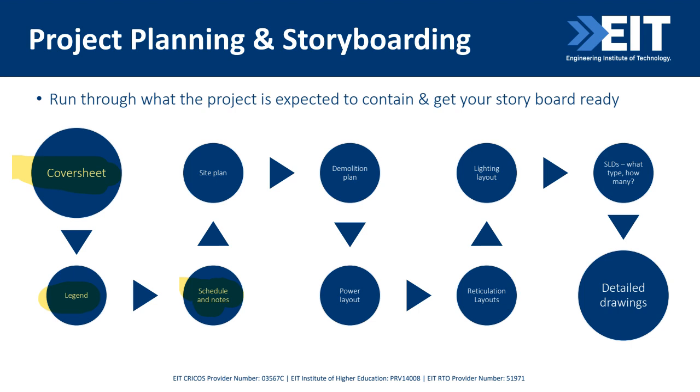One of the key items is a site plan. So this gives you context of what you're doing in relation to the larger area. So it's very zoomed out, you could say, and it gives positions and maybe external information like pits and conduits and street lights. If you're demolishing anything, you might have a demolition plan. You might need to outline what is being retained and what's not.